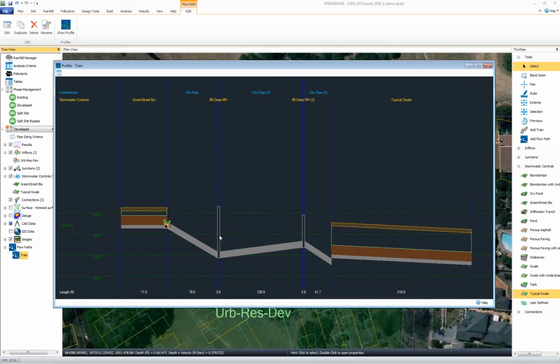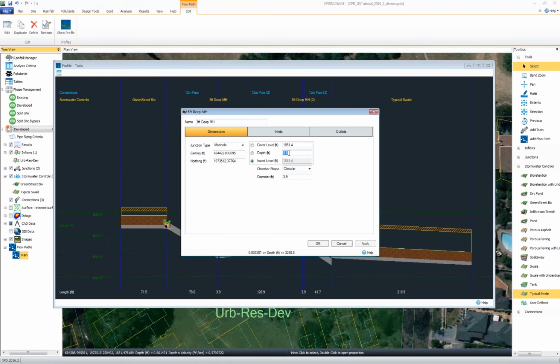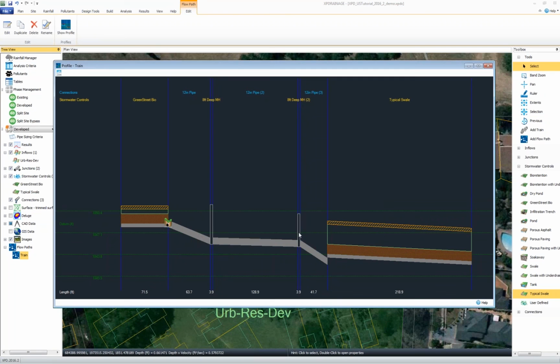Maybe I can update this other manhole, make this again only 6 feet deep. I'm just adding numbers in here to show how this system drains. Even if you have the manholes in the pipe system laid out, you could update this. The connections, the daylighting out into facilities, it seems like it's so hard to track, so easy to drop. This is such a clear way to see how this would not be right.